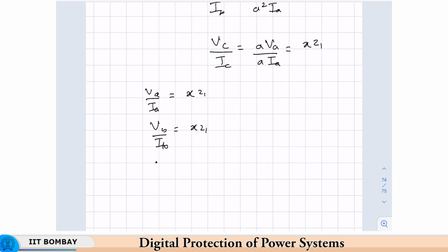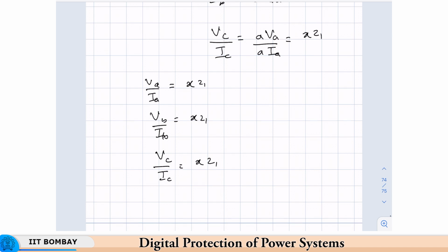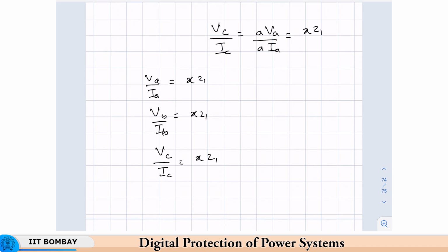This is your line angle, this is your line AB or whatever line that is, theta is your line angle, and what we are saying is if the impedance is less than the positive sequence impedance of the line, and this is your distance x here, then it means that there is a fault. We will elaborate on this towards the end of today's lecture.